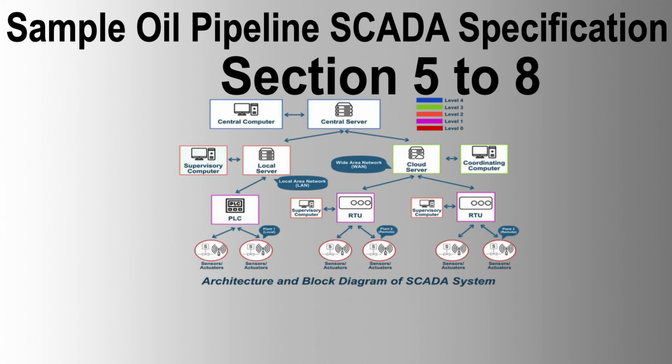6.3.2 Identification. Each cabinet shall have an identifying nameplate fixed on the front and rear with screws. The owner's tagging system shall be used. Internally mounted equipment shall be clearly identified by nameplates using Traffolyte-type WBW labels. Nameplates shall be engraved and secured with self-tapping screws.